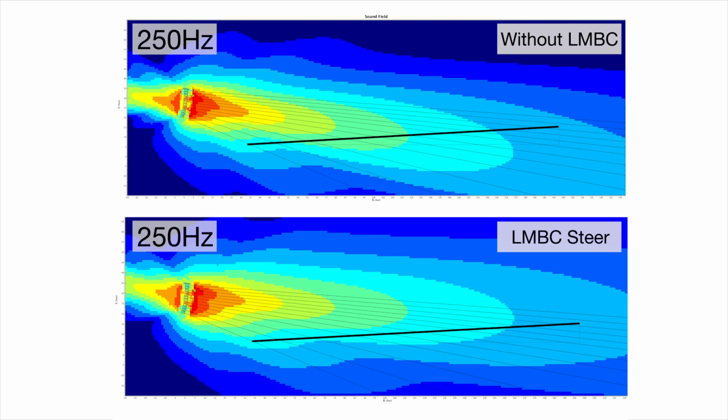These filters can selectively delay a limited frequency range without affecting those above. This allows us to phase steer the low-mid beam without affecting the HF coverage. We're using targeted phase steering to reshape this limited range of frequencies into compliance with the HF range.